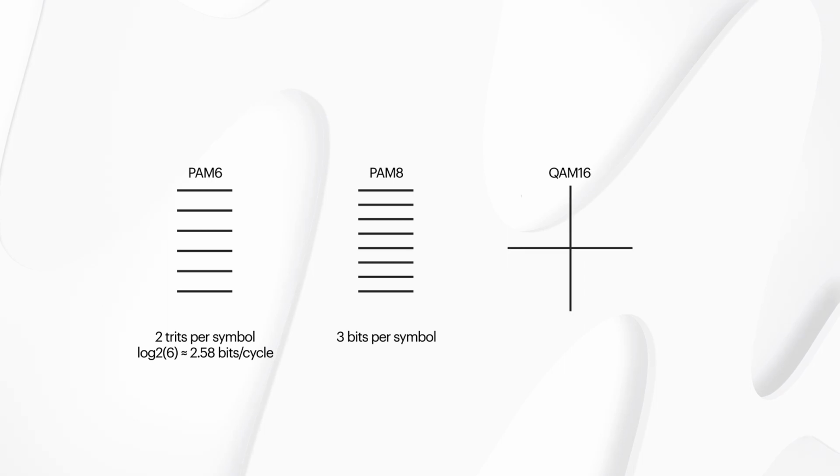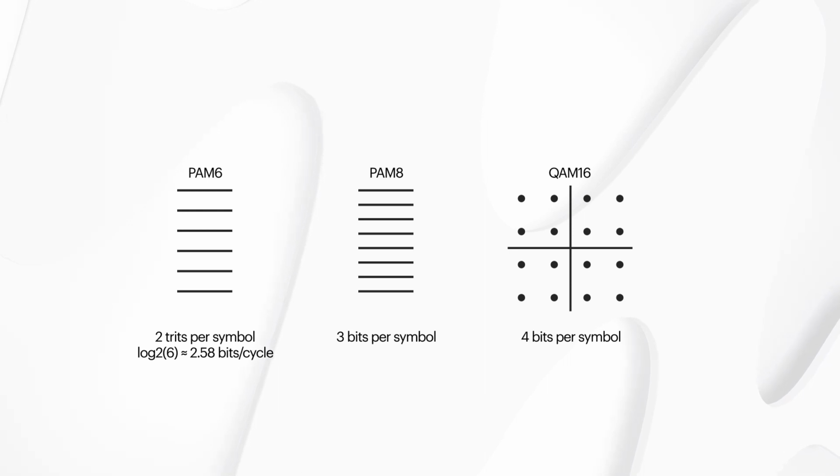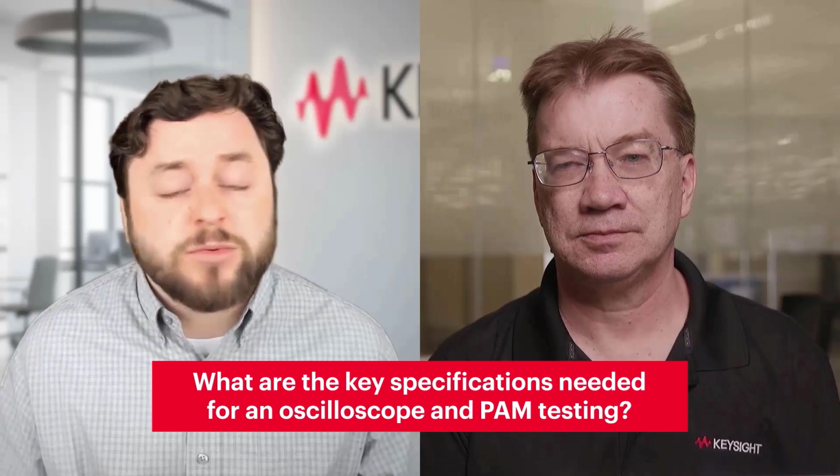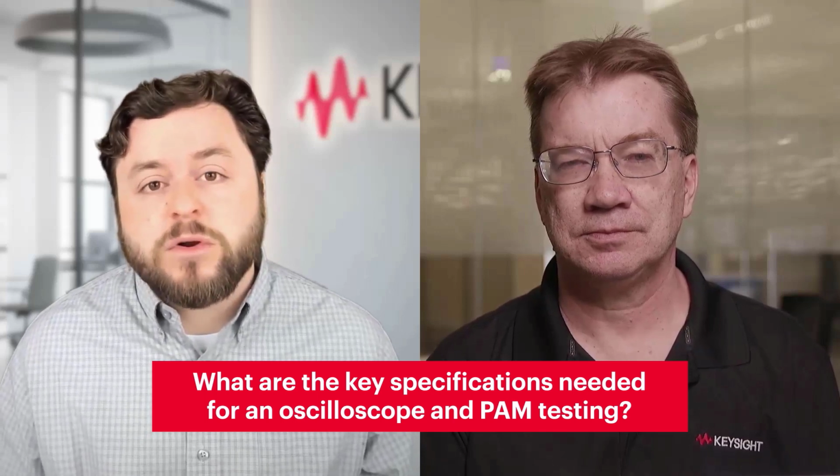It's completely different in the sense that it uses quadrature amplitude modulation, QAM, which is really PAM in both the vertical and the horizontal axis. So if you have a PAM4 I and a PAM4 Q signal, that creates 16 different possible combinations in quadrature, and that's QAM 16. So what are some of the key specifications or requirements that you're going to need for an oscilloscope